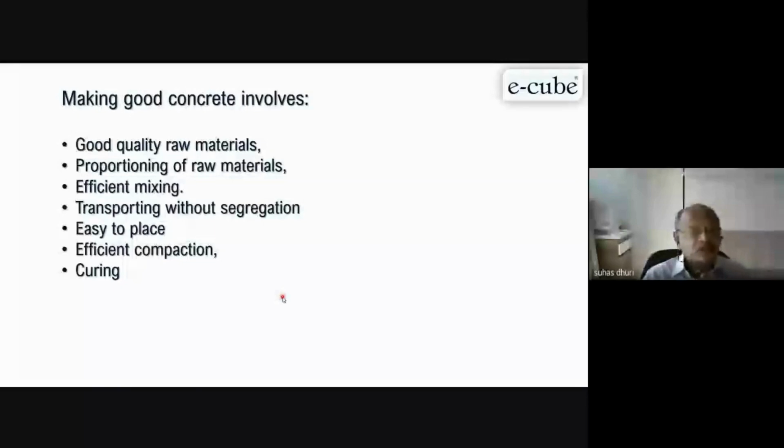Fine to coarse, because we do not get exact quality of the raw materials like fine and coarse aggregate. Now fine aggregate also we get only from the quarries, that is crushed stone sand. So they are not consistent in nature. So once the fines ratio or grading has changed, or shape has changed, one has to change the proportion of your raw materials. It's very, very important. Otherwise, we will have a lot of issues in concrete.